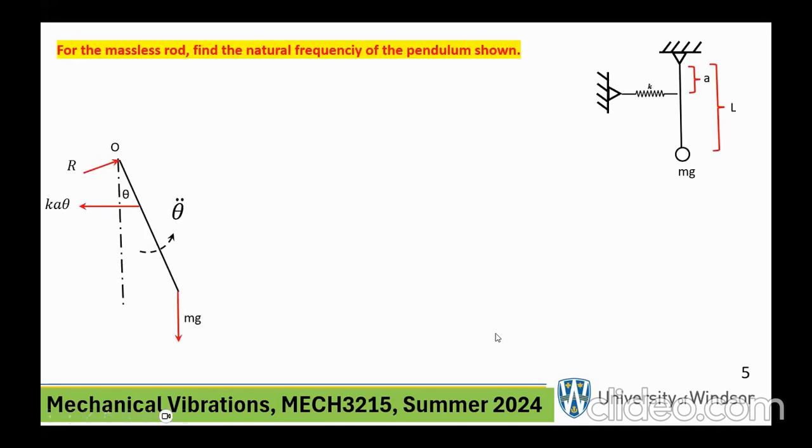Now, let's start with a problem where a pendulum has a perfectly rigid rod, and attached to it is a point mass m g, and on the top there is a spring acting. When you think about this, it is a single degree of freedom system, because if you take the mass and move it to the right, by just simply moving it to the right or giving that rod a certain specific rotation, the entire configuration is determined. So this is actually a single degree of freedom system.